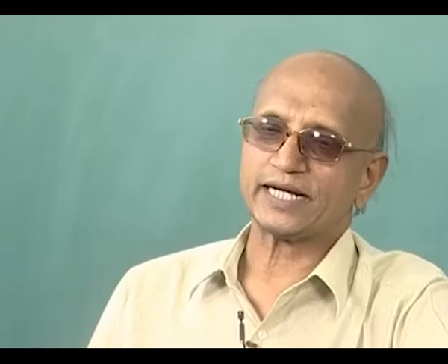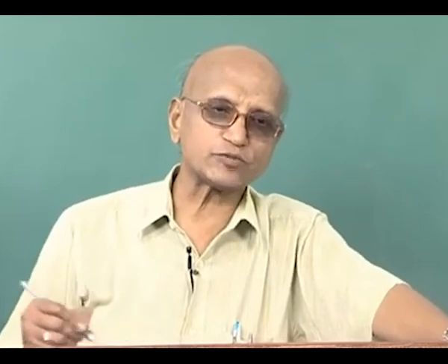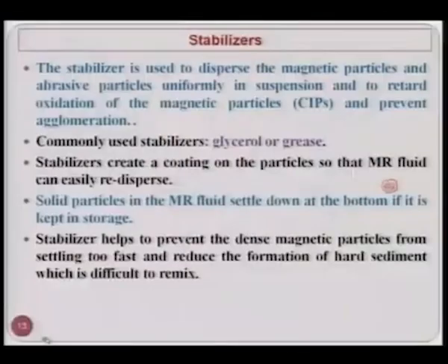So, the tendency is to settle down at the base of the container, but these stabilizers also help in minimizing the tendency to settle down, and secondly, before using any medium it should be uniformly distributed. These abrasive particles should be uniformly distributed. For this, as I will be showing you in the video film, they should be uniformly mixed for at least 1 hour before they are used.